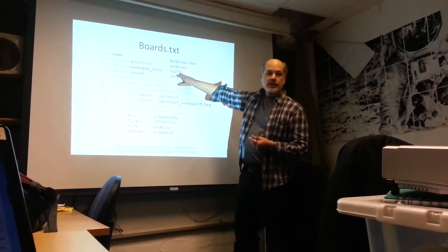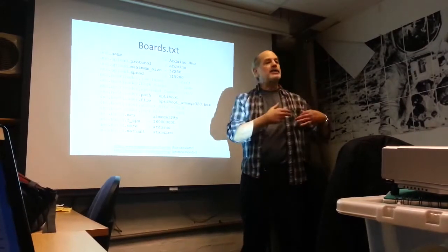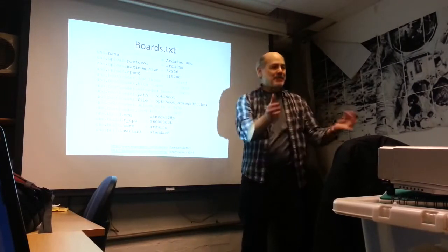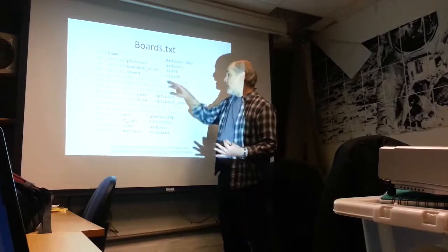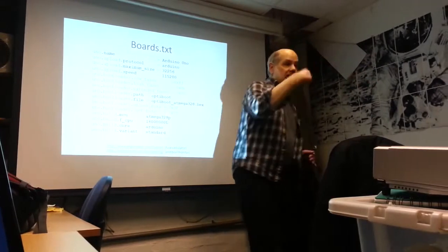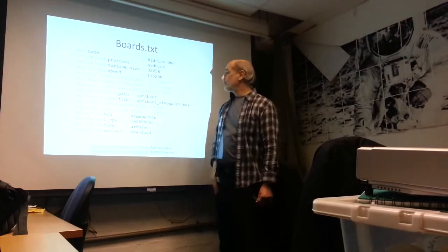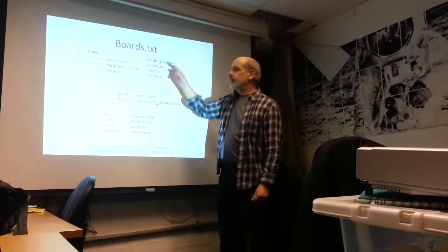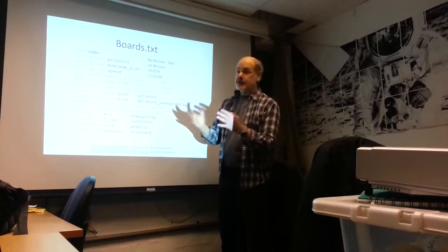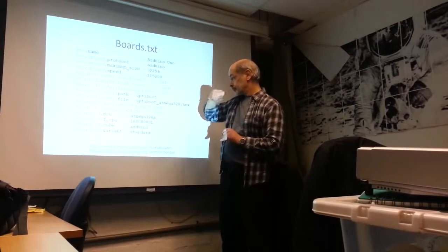The maximum size of a program file, so when it tells you that your program is too big when you're compiling something. Anybody compiled something and it says the program is too big? Wow, you guys need to make bigger programs. But you'll see when you do the compilation, it'll say X number of bytes of however many. The amount free is given by that, because that number is dependent not only on the chip that is being used, but also on how much space the bootloader itself requires. Then there's how fast the serial connection is for the bootloader.